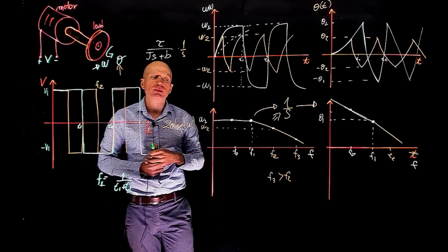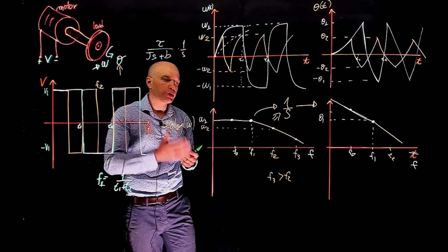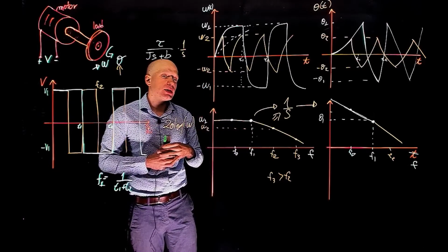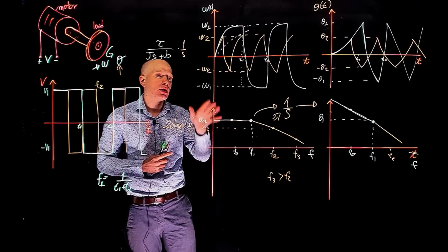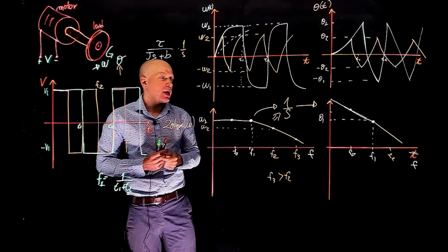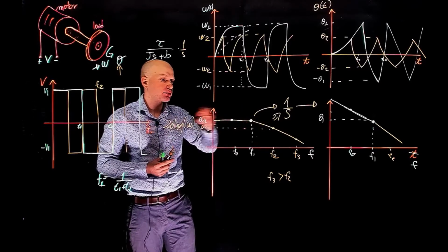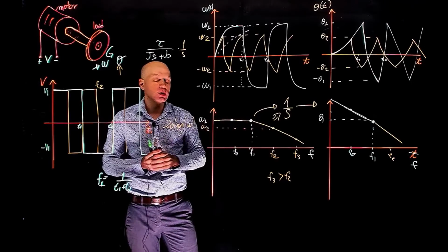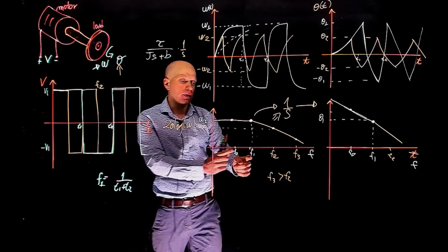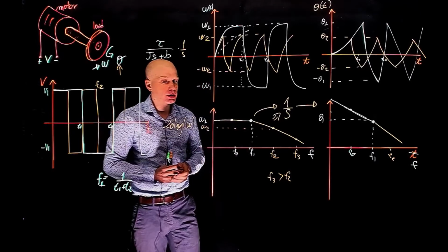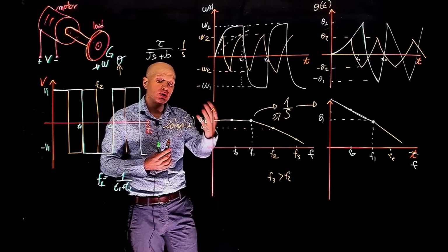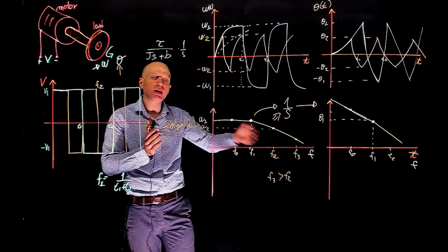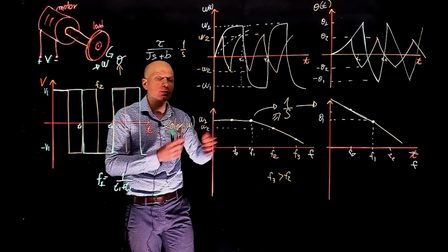What can we conclude from this? Well, we'll notice that when you buy motors, when you buy electrical components for your robotics or mechatronics projects, they will all come with a Bode plot. And they are there for a reason. The reason is that their Bode plot tells you at what frequency those components will operate. Imagine that you want a robot to do some sort of pick and place task. And you want that pick and place to occur at a frequency of, say, 10 Hertz. If your cutoff frequency here is too low, say 1 Hertz, then you will have to increase the magnitude of the input by a very large amount in order to get the displacement you want at the output, the magnitude of that displacement or speed at that particular frequency.